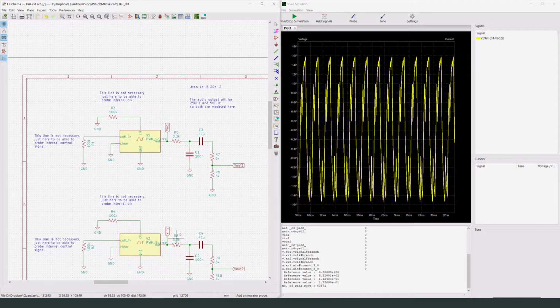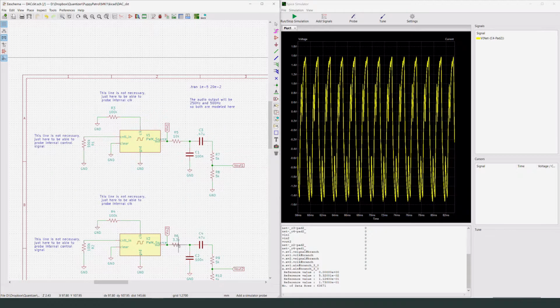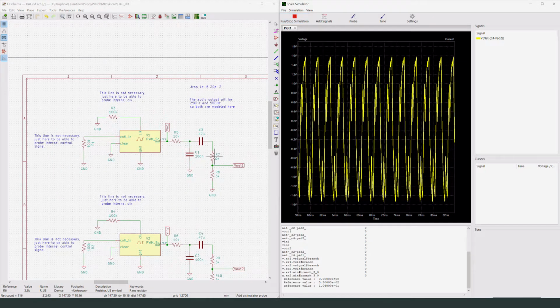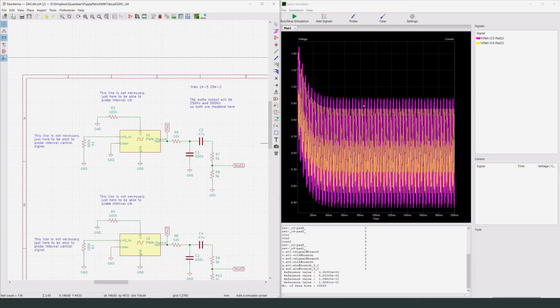And what would happen though, if we decided to go with something that would give us a smoother value, you will see the negative that shows up in that situation. So if we run the simulation again, and now let's probe both of these guys, you'll see as we zoom out that the higher frequency value is now at a noticeable, in fact in the audio you'll be able to tell, maybe not a whole bunch, but you'll be able to tell that they're at different volume levels just because of the filter characteristics in our circuit.